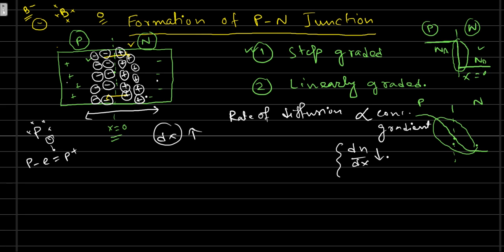And we can give one name, due to the presence of these fixed positive and negative ions. See, one layer is created which contains no free charge carrier. All charges are fixed. Those are ions. They contain positive and negative ions. Okay, all those are charged, but they cannot conduct current because they are fixed. They are not free. Current conduction is possible when there is a free carrier, not fixed. But those are fixed carriers. So they create the layer, so this is called the depletion layer.